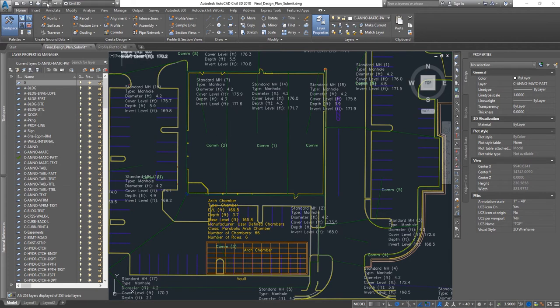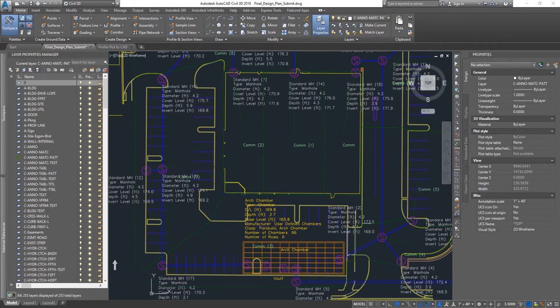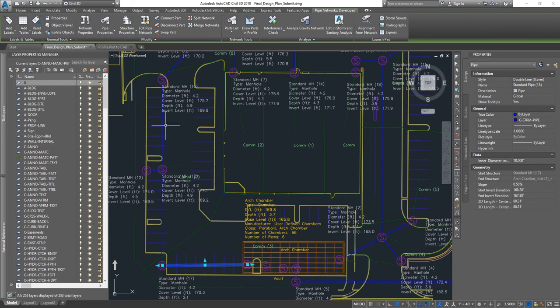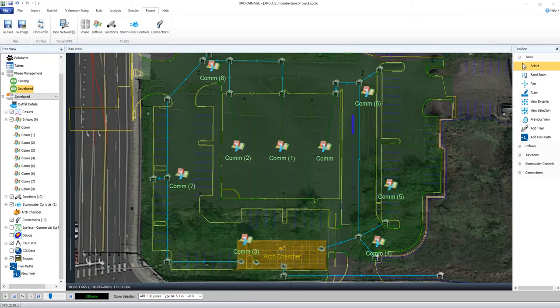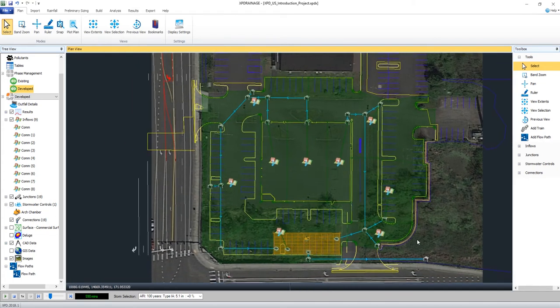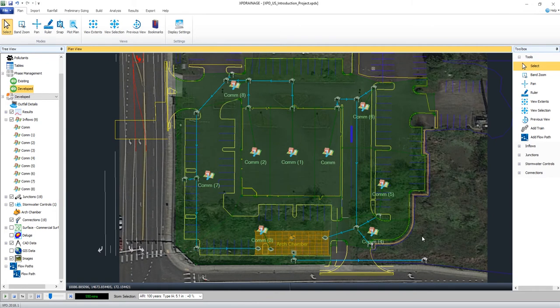So in CAD, this is what we're looking at. I have a CAD file where I've brought in the LandXML pipe network. We can see here that all the vertical attributes associated with that element are brought into this CAD file. You'll see slope, lengths, inverts, and so on and so forth. So it really just takes a couple seconds to export all of the plan and all the pipe network out to CAD. And really, it's the final site information in all its 3D attributes in one go.